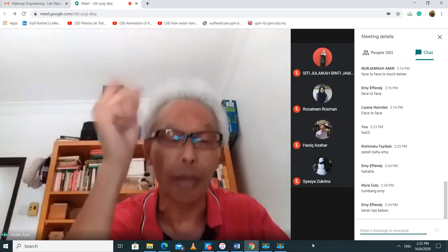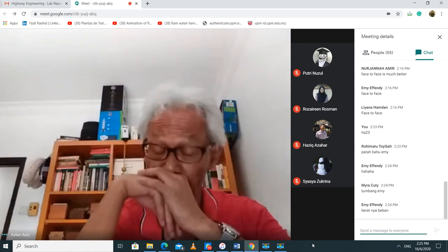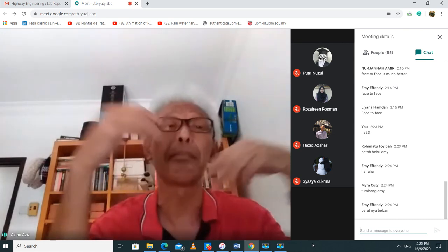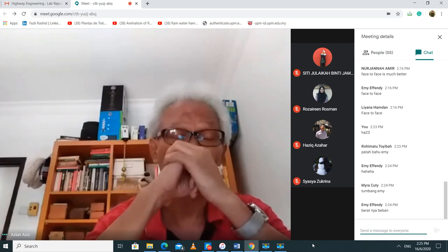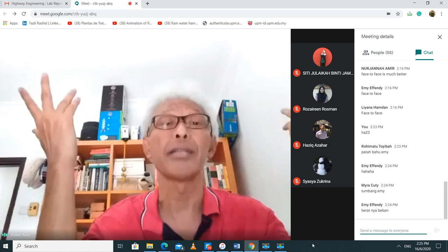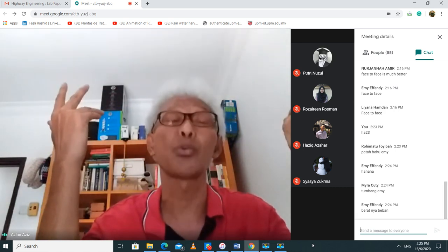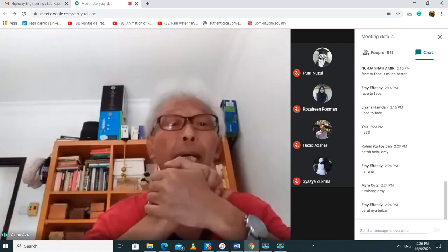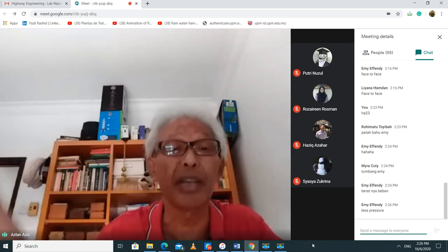Okay, this is normal. Now you come along and you excavate that clay layer. So now Amy is still down there, but you have removed Mira, you have removed Rohimatu. So now Amy says, wow, there's not much weight on me anymore. All right, less weight on her. And why did you excavate? One of the reasons is because you want to make a car park. All right, you make a car park, so you have less weight, less pressure now.